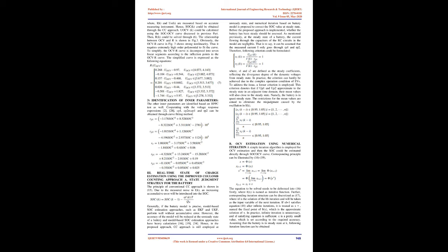Therefore, the constant current discharge (CCD) test was carried out to obtain better accuracy. During the CCD test, the battery was discharged from 100% to 10% with the discharging current of 0.8 A. Consequently, the discharging process would last more than 3 hours. As the Li-ion battery can reach its steady state after only a few minutes [14-16], the transient process into steady state can be neglected compared with the whole discharging process.